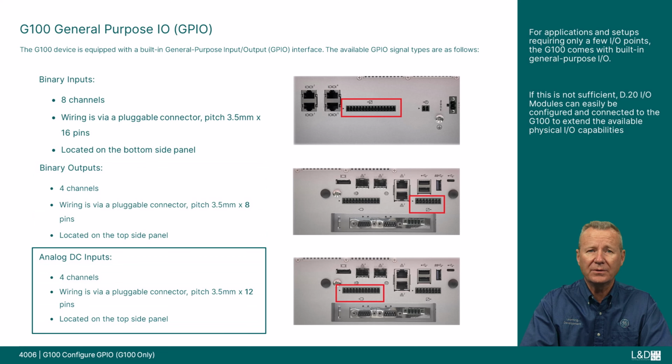All GPIO binary input channels are wetted internally from the main power supply circuit using a single common. Each DI channel can be triggered by NO (normally open) potential-free external contacts, with the wetting positive voltage being switched through the external contacts. The DI voltage supply is the same as the G100 power supply, 12, 24, 48 volts DC, with each DI channel consuming typically 5 milliamps. Note, the DI wetting voltage is protected internally by the main fuse.